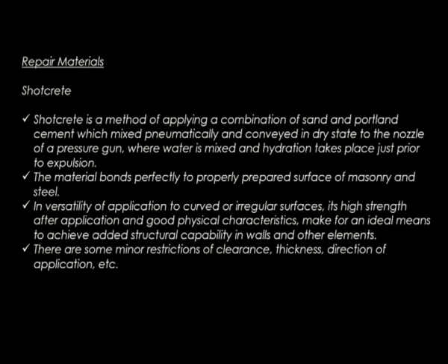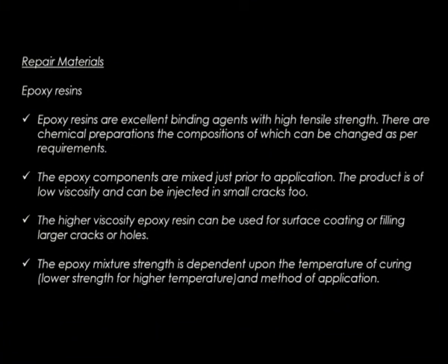In applications of curved and irregular surfaces, it shows high strength after application and also good physical characteristics. That is why this is used. And epoxy resins can be used from small quantity to high quantity, usually whenever there is a large crack or hole, and wherever there has to be some filling to make it look normal. Whenever it has to be a plain surface, we use the epoxy resins to fill the crack or hole and make it completely new.